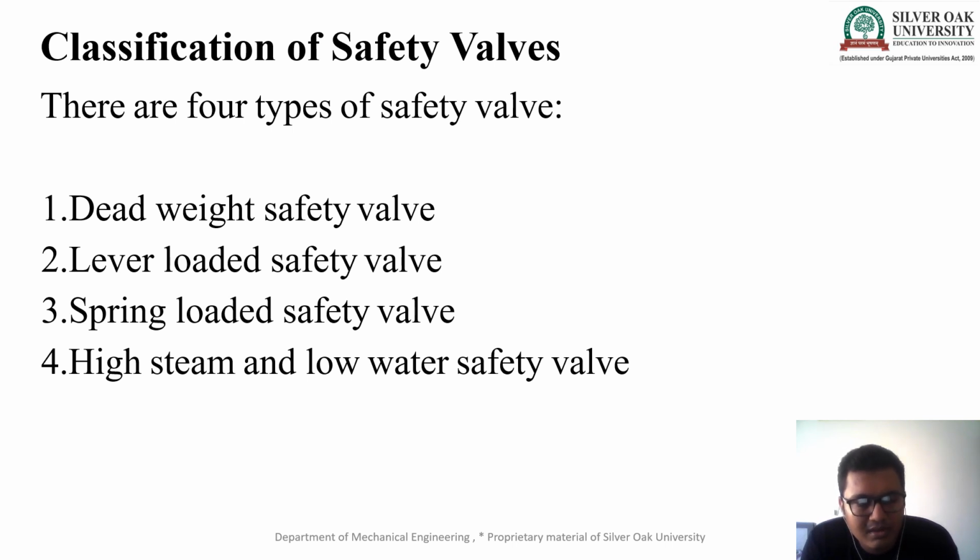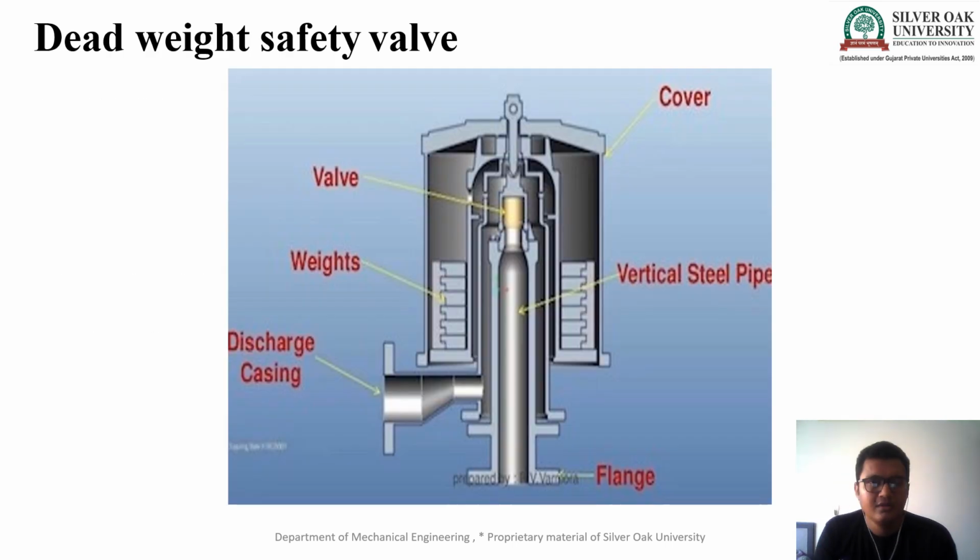If the steam temperature or pressure is high, then the safety valve will get operated. And if the low water level indicates the water level is below the normal water level, then also the safety valve gets operated. First, we discuss the dead weight safety valve.